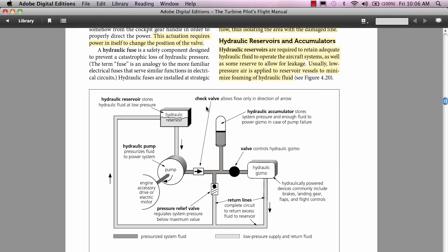Now, from the electrical section, we know that the RAT is called the ram air turbine. And we'll see that aircraft also have ram air turbines for the hydraulic system. And apparently he had to deploy the RAT to use on this aircraft, plus he had to use the accumulator backups to get the aircraft down safely that night.